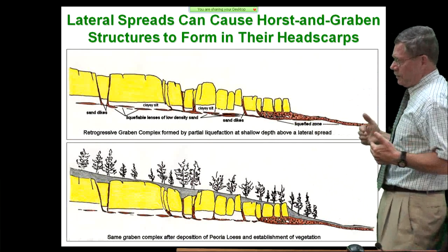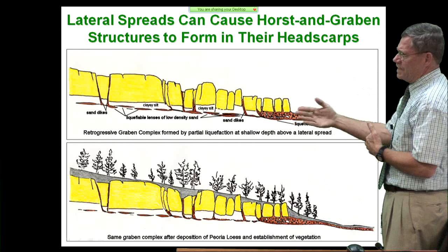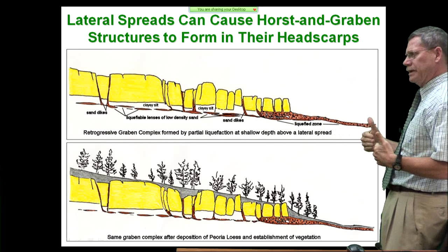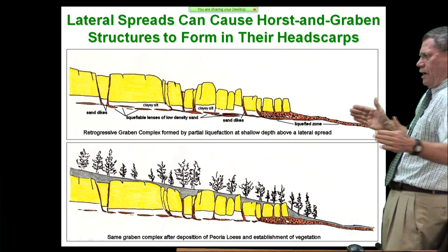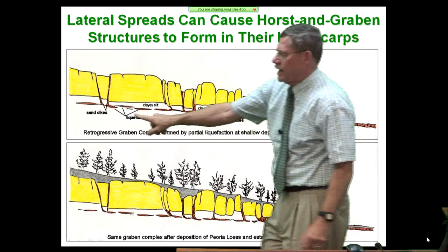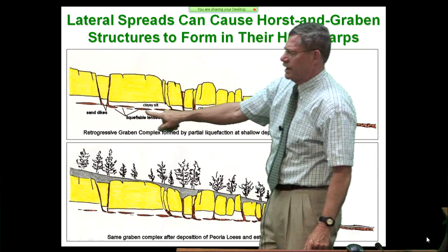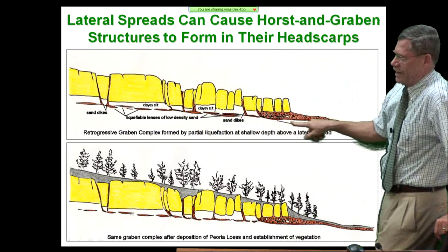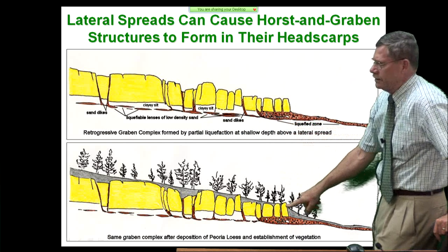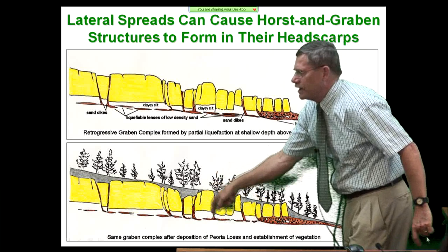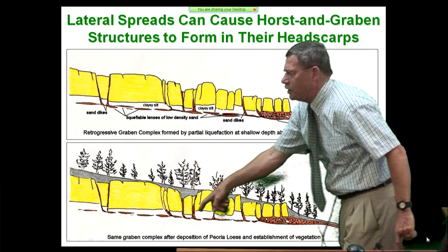If you get back from it, these are my sketches down near Holly Ridge. If you look at it from a large scale point of view, what you see is you probably have lateral spreading occurring along some kind of surface down here, and you're seeing this Horst and Graben type of sequence, which these are all getting mapped as separate faults.